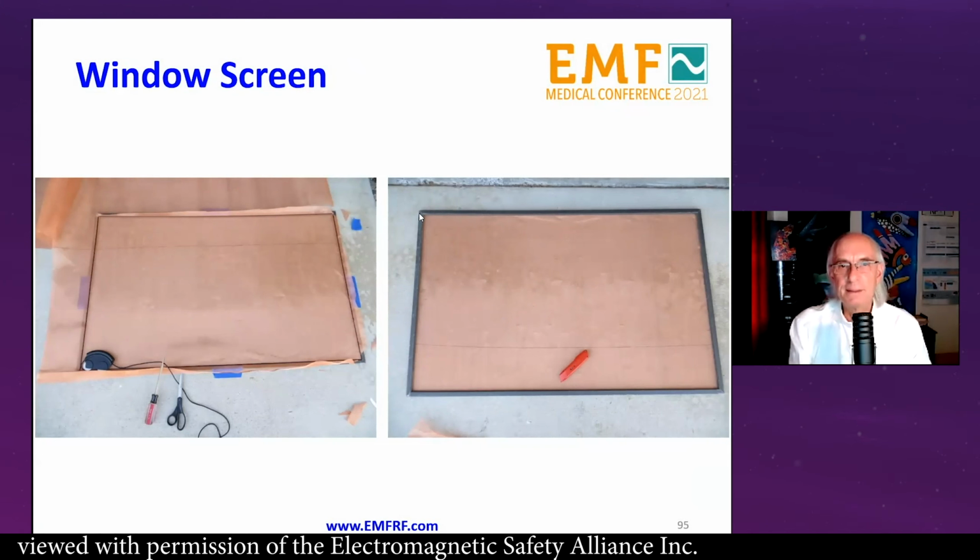Well, you could make this larger than your window, overlapping the entire size of your window, and attach it to the outside of your building, and then you have a very highly effective shielding material to deal with your windows. Windows are the largest hole in a building envelope when you talk about radio frequencies, unless you've got double pane glass with an E rating.